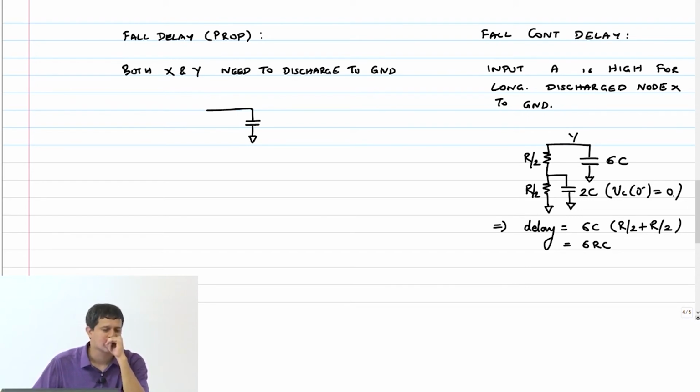True. So that's where the approximation that we made for this Elmore delay model comes in. It is true that this node, for it to accommodate some current, will actually bump up slightly. So this is only an approximate answer. It's not an exact answer. That node has to bump up slightly to allow some current, and therefore you will have some charging of this capacitor also slightly in the process and all that stuff.